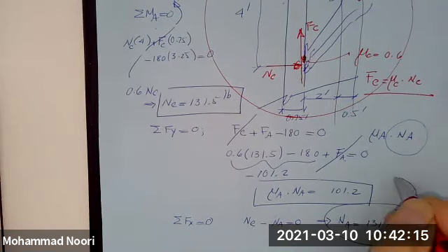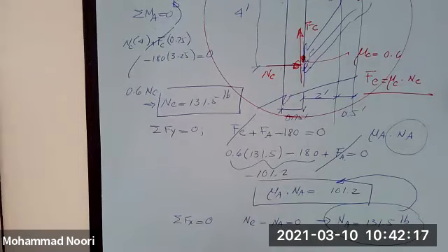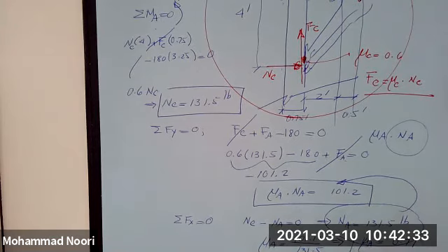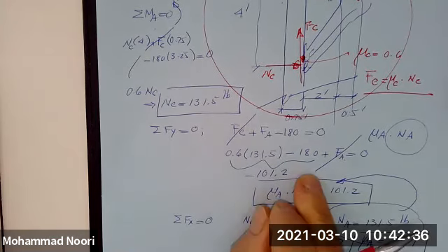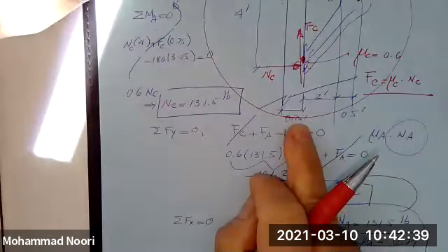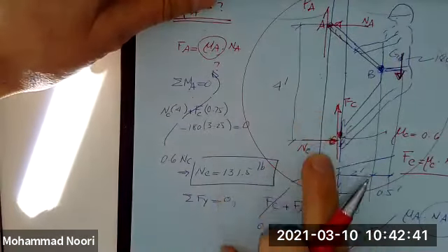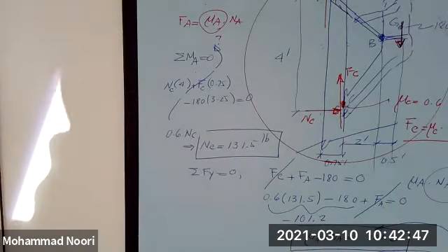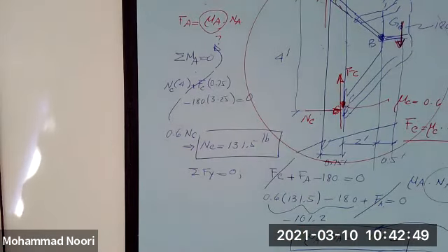If I substitute that in here, I get mu sub A as 101.2 divided by 131.5, which comes out to be 0.77. So in order for this guy not to slip down this light pole or power transmission line pole, he needs to have a supporting belt with a minimum coefficient of friction of 0.77.